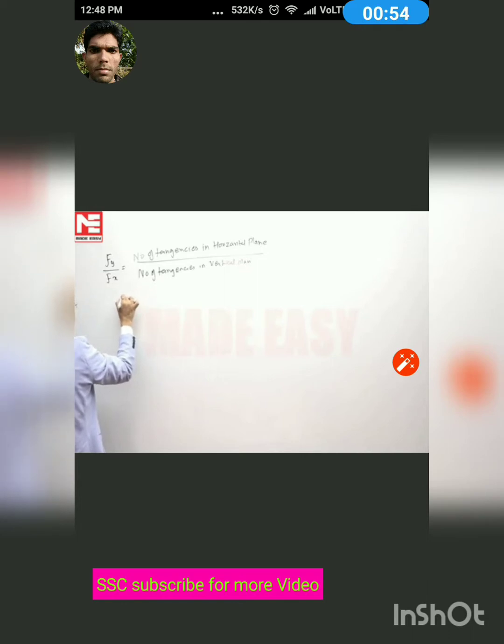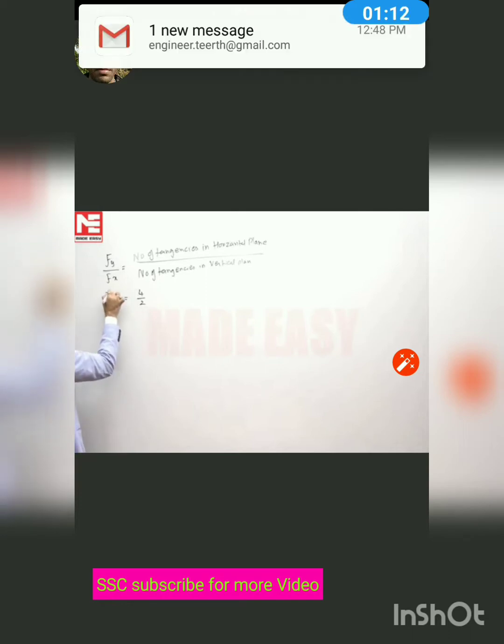which in the numerical has been given as the number of tangencies in the horizontal plane is 4 and the number of tangencies in the vertical plane is 2, and the frequency of the vertical input is 2 kilohertz, and we are asked to calculate the frequency at the X plates. So this is going to be Fx, therefore it is going to be equal to 1 kilohertz.